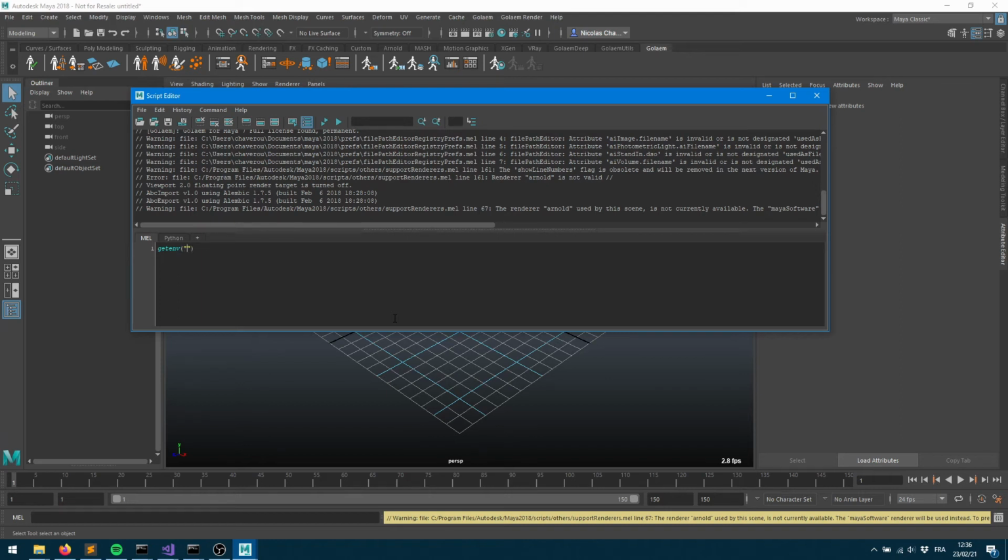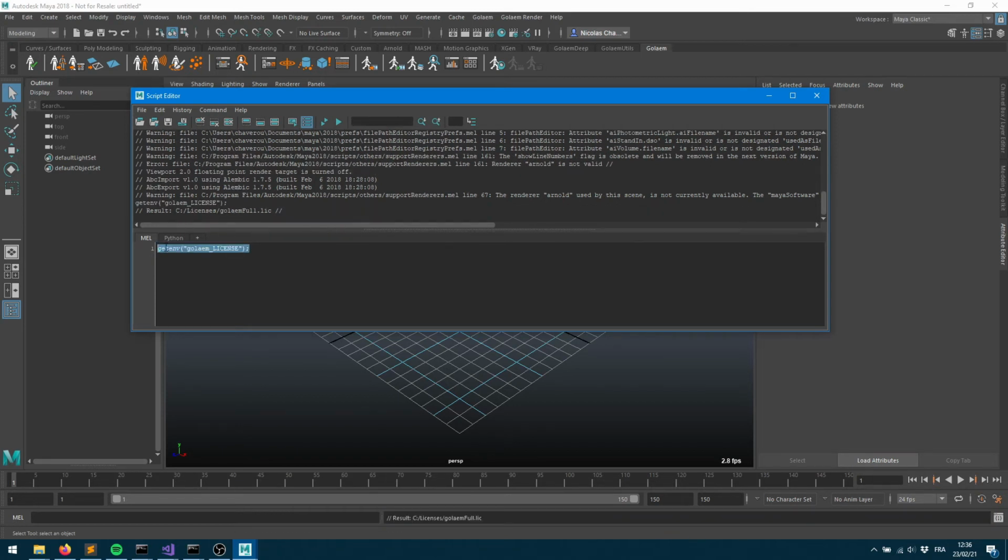If you want to troubleshoot anything, some best practice is also to check from your Maya session if your environment variable has been set properly. So in MEL, you can use the getenv command, and with double quotes you can put any name of environment variable, put a semicolon at the end and evaluate, and now you're asking, okay, from this Maya session, what's the value of this? Sometimes you can have some mismatch, where the value of the environment variable is not set properly or has not been updated properly. So by using it in your context, you can check if it looks proper.